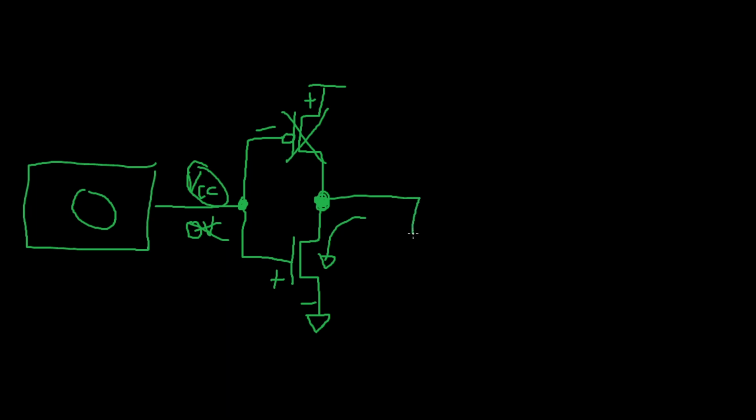For example, if we connect a capacitive load, and let's say we have a 5-volt system here, if we were operating at 5 volts, then our capacitor would be charged to 5 volts when the output's in the high state. And when we switch to the low state, we assume that this switches very quickly, within nanoseconds.